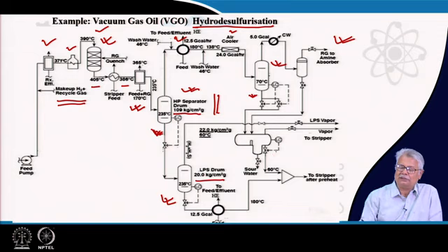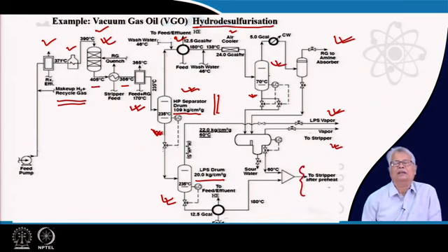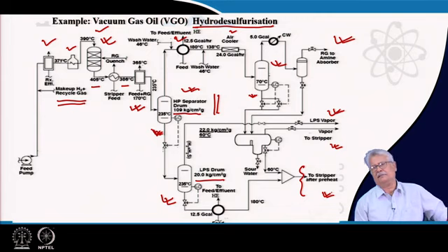Here again some more amount of vapor which is from the low pressure separator comes out, and here we have the vapor which is finally going to the stripper, and your bottom product here is finally to be stripped and it goes to another section after preheating. It is basically going to a stripper which is nothing but a column, and naturally in order to facilitate stripping you add heat, that means you preheat it.